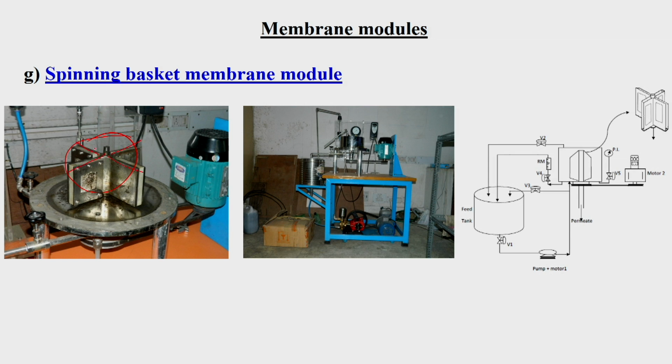These are hollow agitator blades, all connected with one common header, the permeate collection line, and on one side of each agitator blade the membrane is placed. So, we have 4 membranes on 4 different blades in the same orientation, and the common header